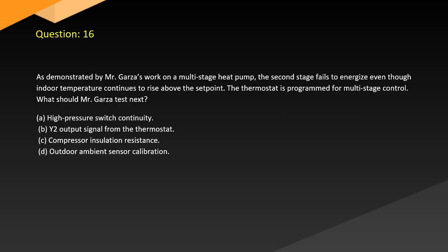Question 16. Demonstrated by Garza's work on a multi-stage heat pump, the second stage fails to energize even though indoor temperature continues to rise above the set point. The thermostat is programmed for multi-stage control. What should Garza test next? A. High-pressure switch continuity. B. Output signal from the thermostat. C. Compressor insulation resistance. D. Outdoor ambient sensor calibration.